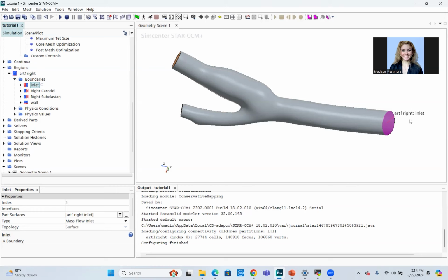And then you can take those values that you calculate in your circuit at any point, and usually you'll have to open it up if you want to couple the two together. But in our case, I didn't. I just said, at this point, I'm going to calculate with my circuit. That's a circuit that one of our grad students way in the past made. We're going to get our mass flow coming into this chunk here, coming in right here, and then calculate the pressures where it's coming out, also from that circuit. And then we're going to assign those values to this. And this is now unsteady. So this is not a steady state simulation.